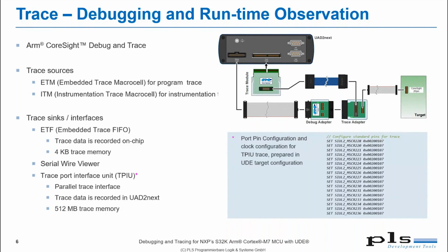Tracing, you may know, is especially useful for debugging if you can't do stop mode debugging anymore because you have parallel execution, or some timing issues in your application, and whenever you break the application, you get an inconsistent state, or the issue that you want to observe is hidden by your break. So tracing is very useful if stop mode debugging has a negative impact on the application's behavior.